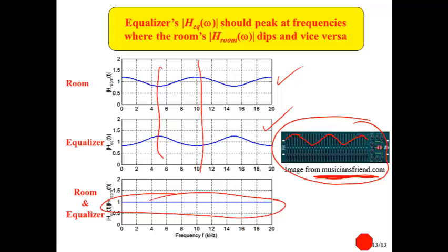The cool thing is that each one of those sliders allows you to pick how much attenuation or boost occurs at the corresponding frequency. Each slider is labeled with a particular frequency, so this is a rough generalization, but the basic idea is that the shape of the sliders outlines the shape of the frequency response of the system that you get.